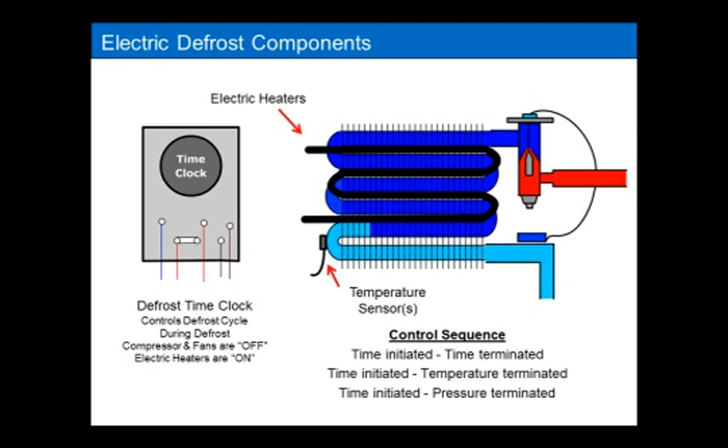So don't misjudge how important the right heater to use is. The heater has to be sized properly for the evaporator. Even though it's a pretty basic resistive heater, it is designed specifically for the coil. It has the right wattage based on the linear distance being used. It is affixed to the coil in the manner the manufacturer designs. So it's simplistic in how it works, but when replacing it, you want to make sure you use the right resistive heater.